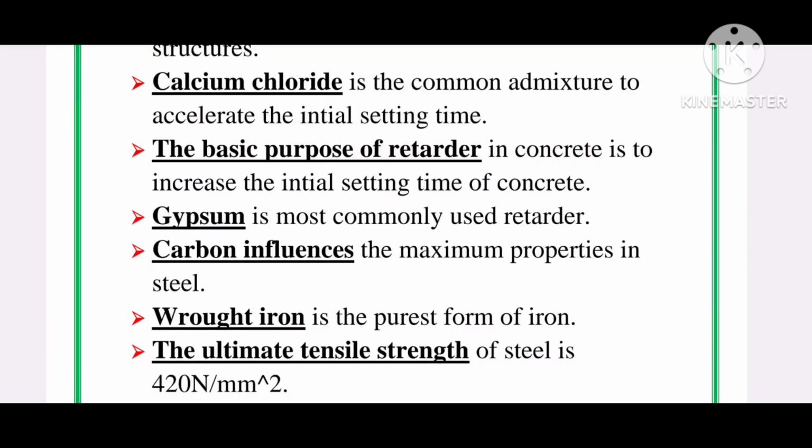Next point, calcium chloride is a common admixture to accelerate the initial setting time. The basic purpose of retarders in concrete is to increase the initial setting time of concrete. Gypsum is the most commonly used retarder.